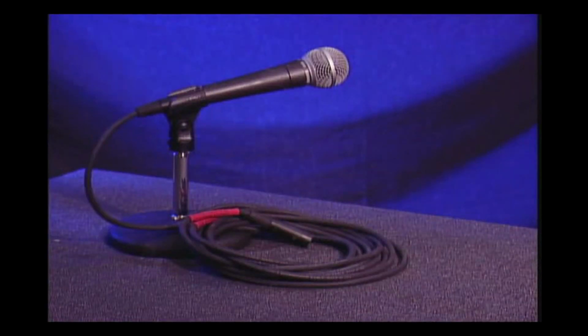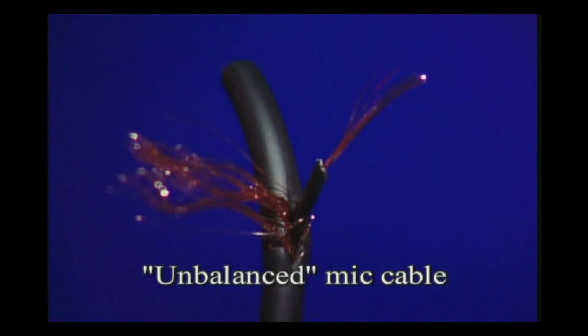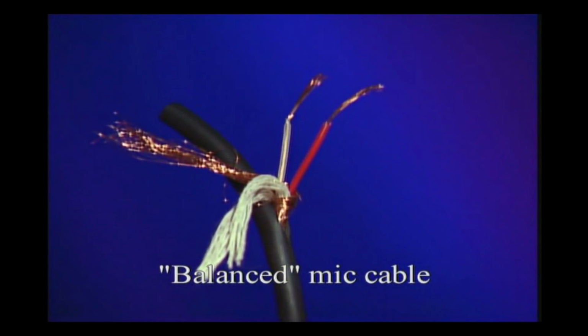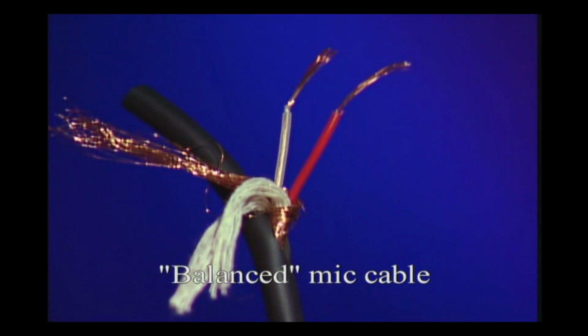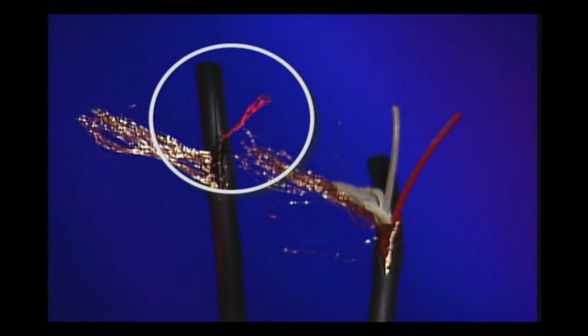Microphone cables carry the audio signal to its destination in either 2 basic ways. Unbalanced cables use one of the signal-carrying conductors as a shield against electromagnetic interference. Balanced cables use matched signal-carrying conductors with a 3rd conductor surrounding it as a shield. Although unbalanced mic cables are cheaper and reasonably effective over short distances, there are 2 disadvantages.